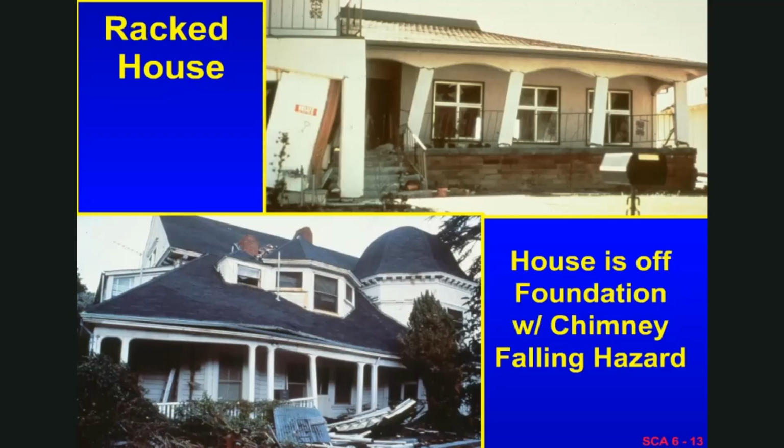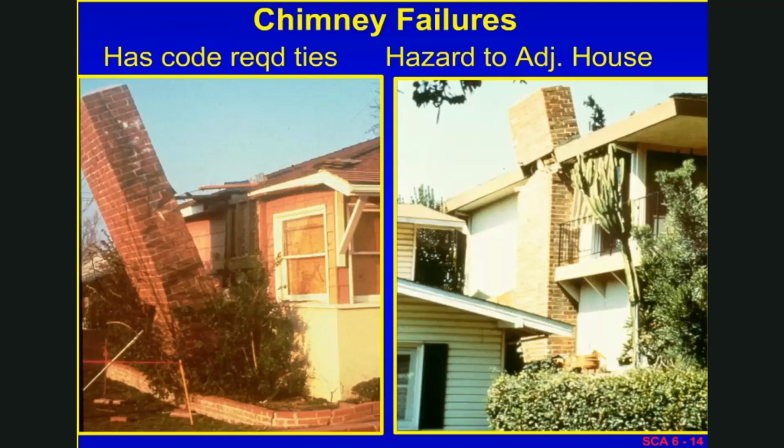The electricity needs to be turned off. A special warning there is that when earthquakes first occur, normally all the electricity gets turned off because the system goes down. And we in search and rescue have to make doubly sure that we remember, even though everything is off, the whole system may come back on when we're in a structure. So we have to make sure that in each case, at the meter, the proper lever has been pulled and the electricity has been turned off. That hasn't always been the case.